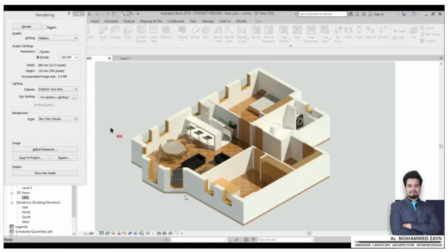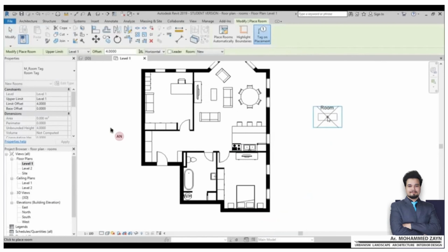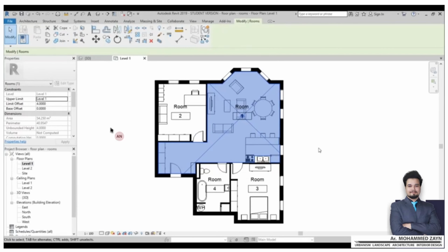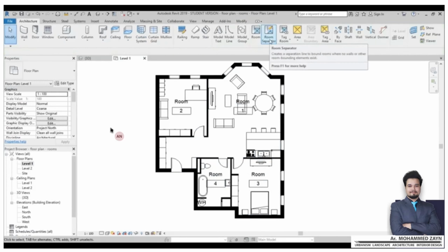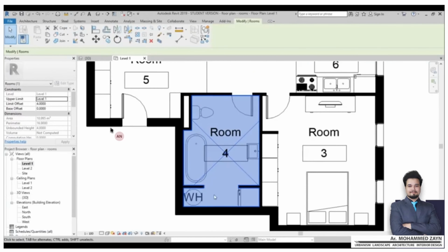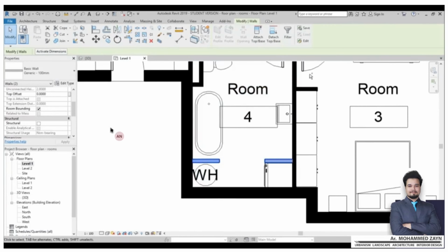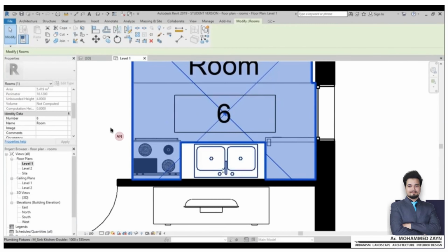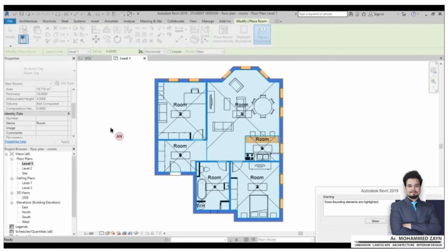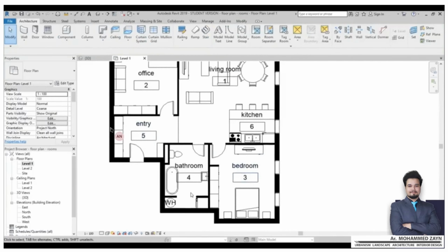So this is a forward video of creating a room legend or a schedule. In this video, you can see how we create a very basic legend and schedule in Revit. For this, you start placing your room boundaries and start naming your rooms. Now you have your area allocations with you. You will start color coding them for ease of understanding. So each room here has a unique color assigned to it. As you start assigning colors, Revit will automatically start making the legend for you. We'll start with the schedule to show information about the room.